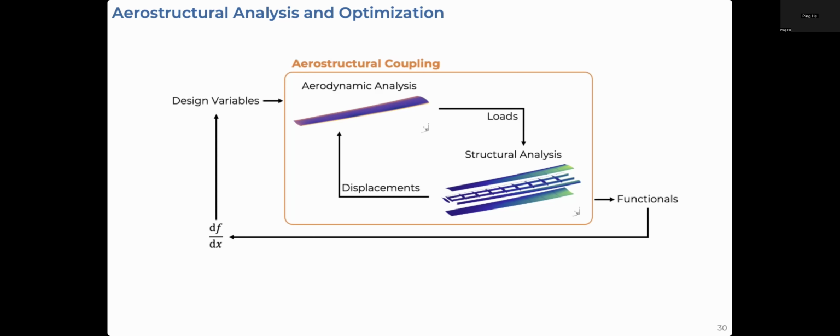Now, propeller aerostructural coupling is a little bit different than conventional aerostructural coupling for a wing, because propellers have a thrust, a torque, and an installation weight that all affect the wing structure. So how do we model this? We look at a clean wing, as this is easier for optimization once we remove the complicated intersections and geometries for nacelles, and we look at a wing box so that it has some spars and some ribs. We connect rigid body elements that allow us to connect to where the propeller locations are and impart some forces and track displacements. With this, we have a simplified version of our wing that we can use for both aerodynamic and structural analysis.